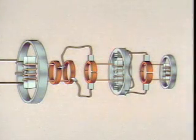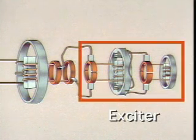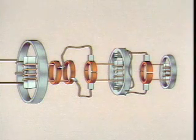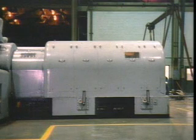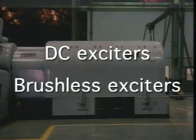In this simplified illustration of a generator, the device that produces and supplies current to the rotor windings is called an exciter. Direct current is used because it is constant, and it produces a steady, unchanging magnetic field. While several different types of exciters may be used in generators, the two types that are used most commonly are DC exciters and brushless exciters. We'll look at the DC exciter first.